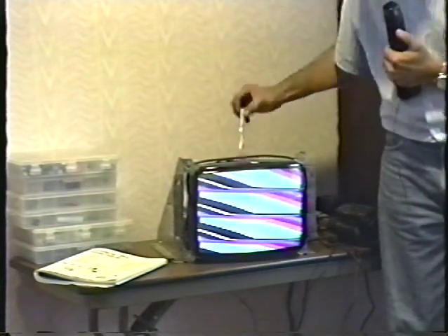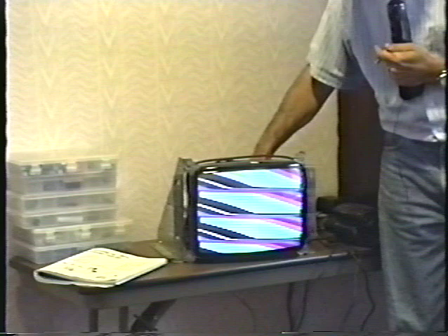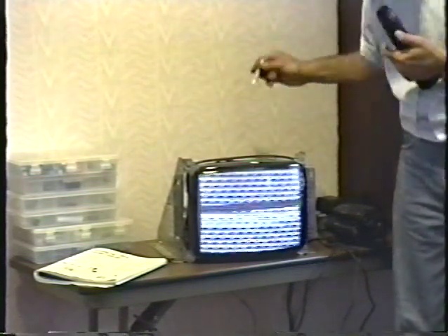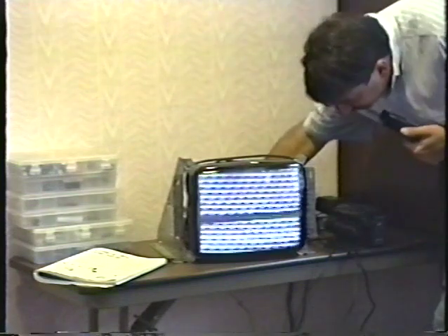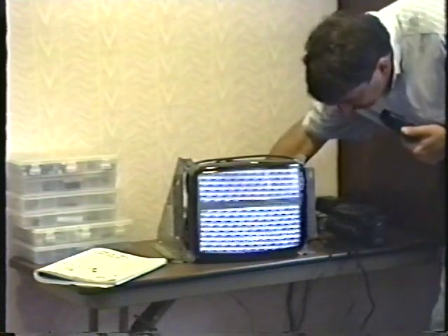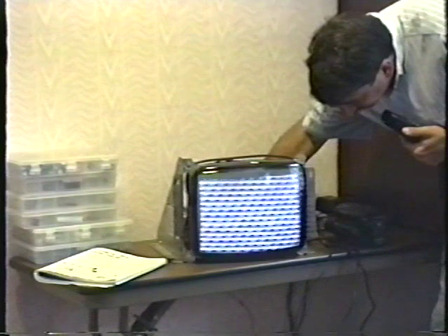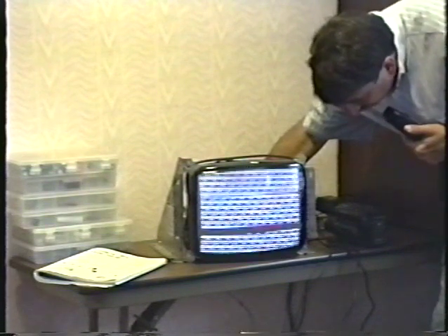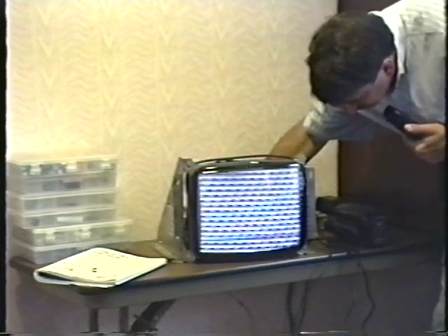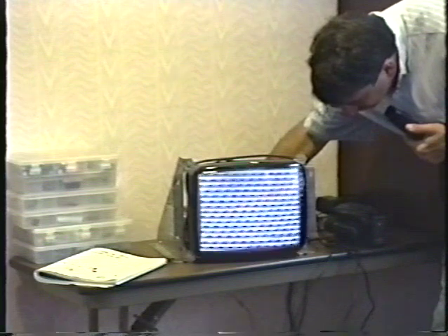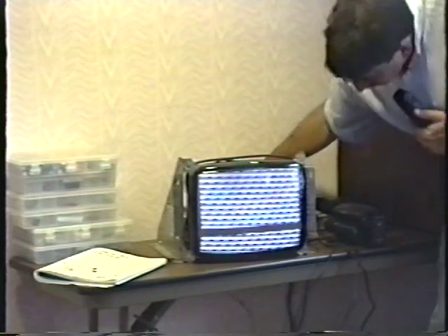Now, what I'm going to do right here is disconnect the sync wire, and we're going to see both problems at once, because this will be a lot easier for me to demonstrate. Okay, first of all, let me try to keep it from rolling vertically, because that's the easiest to do. You see the black bar? I'm trying to adjust it to stop, but I can get it to slow down and never stop. See how it's slowly drifting.